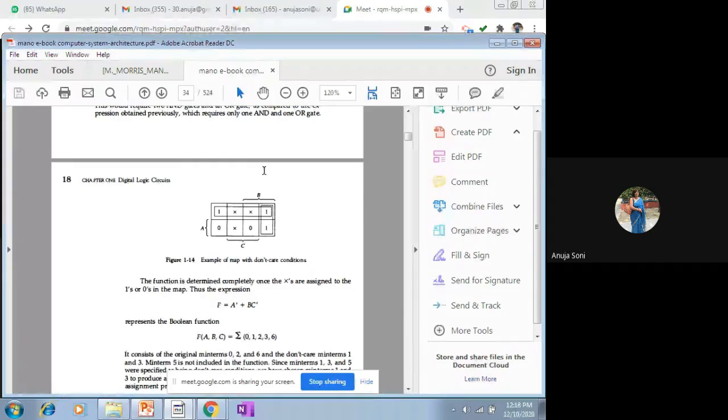So this is the example corresponding to that given Boolean expression. These are the three min terms which are going to produce the value 1. These three are the don't care cells, and other than that, these two represent the value 0. Now, in order to produce the Boolean expression, the groups are combined in terms of integral powers of 2. But wherever there are adjacent don't care conditions, you have to make use of those adjacent cells and treat them as value 1.